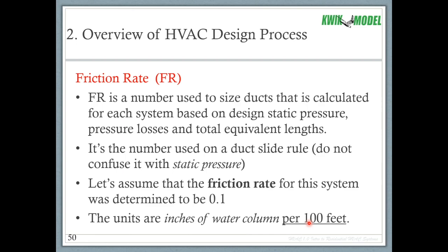Okay, but different parts of that duct system eat up that pressure. They use it up. The evaporator coil eats up a lot of our pressure, and so we need to take those into account. And then another way that Manual D does a very good job of quantifying various parts of a duct system is through something called equivalent lengths. Equivalent length can be the actual length of a duct. How long is that duct? Is it 10 feet, 20 feet, 30 feet long?